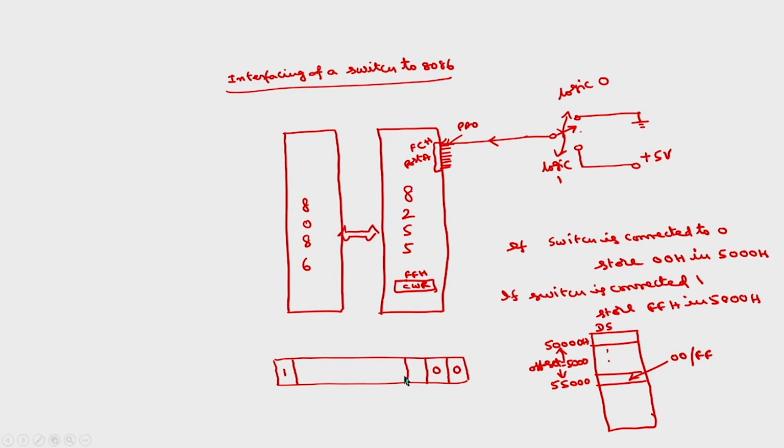This is for mode selection of port B, so I also want to operate it in mode 0. These three are in fact don't cares. Then port C upper, I also want to program as output mode. These are in fact don't cares because we are not using these ports. For the sake of simplicity I have taken zeros. Then what is important is the remaining 3 bits.